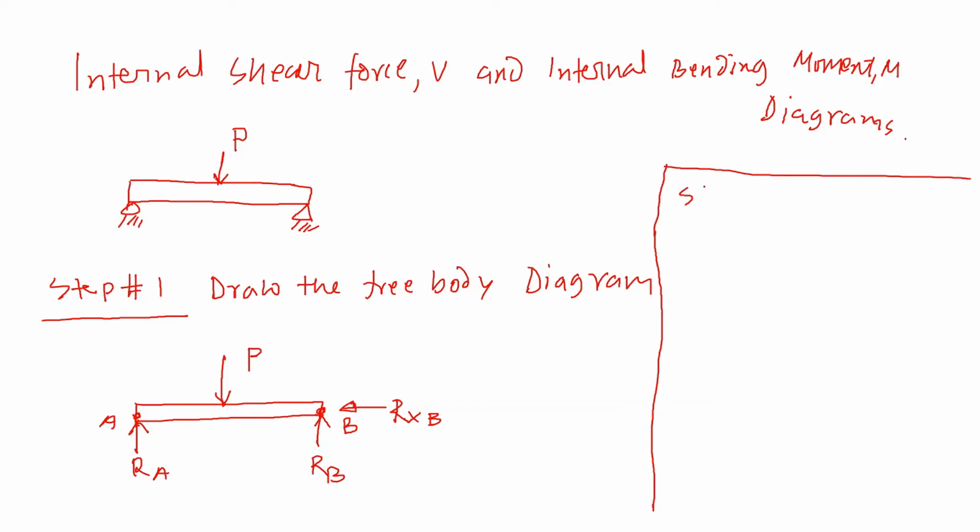Step number two is find the reaction forces, or calculate the reaction forces. As you know, to calculate reaction forces, you have to apply moment.